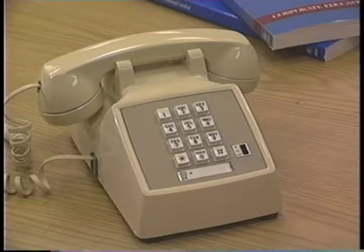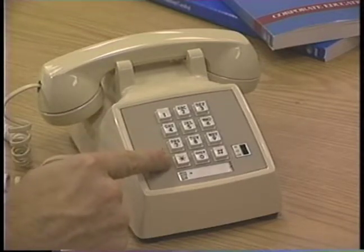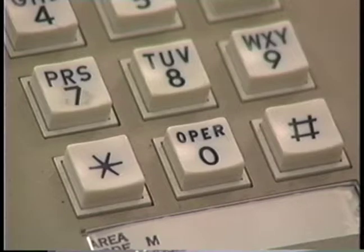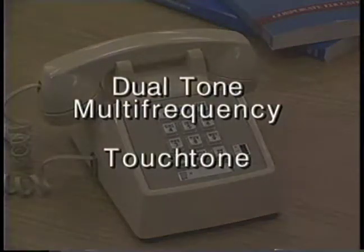The push-button dialing mechanism creates tones of different frequencies. As you can see, this set of buttons, called the keypad, has the numbers 0 through 9 and 2 symbols, the asterisk and the pound sign. Some keypads have other symbols and letters, but we'll focus on this one, since in this type, each number or symbol has 2 tones or frequencies assigned to it. So this method of dialing is technically called dual-tone multi-frequency. You probably know it as touch tone.